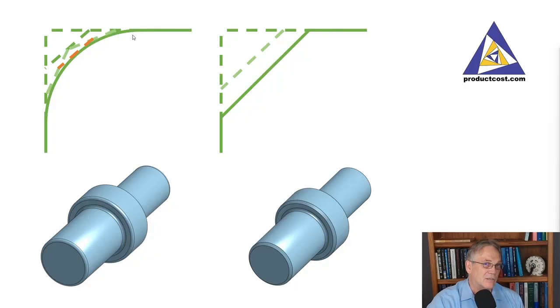This can be alleviated by using a round tool and thus get you to the final shape quicker than if you used a flat tool. But then you would need another tool for that, and that just takes additional resources and having to maintain that tool. So it's not always the case that it's going to take longer to produce a fillet, but for the most part it's going to take longer to produce fillets than chamfers.